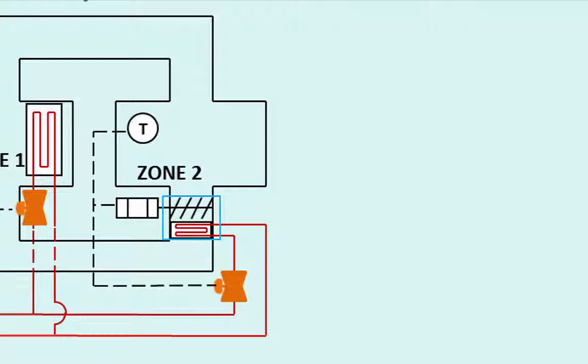to the airstream. The complete sequence of operation for a VAV box will be discussed in a few lessons from now. But for the time being, let's just assume that it is winter, when heating is required. The VAV box controller will open and close this control valve in order to maintain the space temperature. So here's where the control loop differs a bit from that of the preheat coil. We are not concerned about the temperature of the air in the ductwork just downstream of the coil, as was the case back in the air handling unit for the preheat coil.